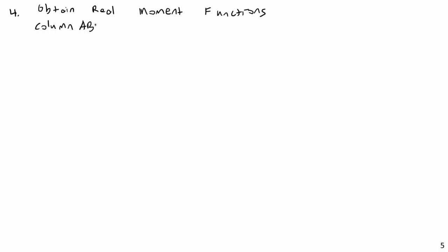We know from statics, mechanics of materials, and other things hopefully that once you have the end forces in a member, finding the internal forces is really easy. It's really just a method of sections at that point. The hard part is getting the end forces. Once you have those, the internal forces are relatively simple to solve for. So let's draw an isolated free body diagram.